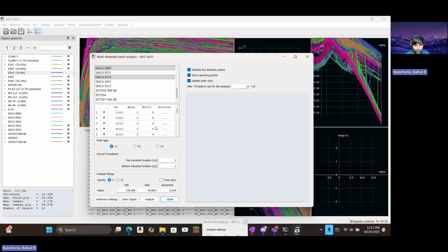One more important thing is when you add or delete a Reynolds number in this box. When you see this action tab, click the three dots. You can say insert after, and it'll automatically give you a Reynolds number, but you can change it. It gave us 1,500, but maybe I want it to be 1,900, and all I do is change it. Yeah, it's as simple as that. And if you don't want it, you just click delete.